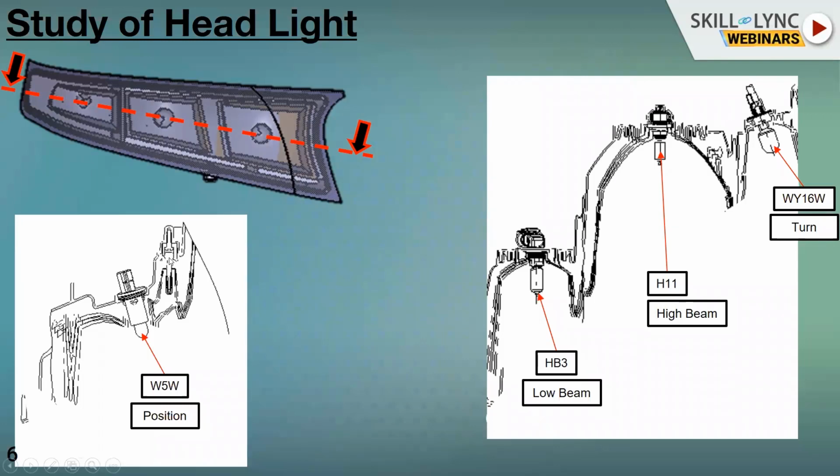For this part we mainly use the PA6 material, that is nylon, because it should be strong enough to withstand the reflector load and hold the reflector. If we go with PC, the stiffness is very low. So we have to choose the right material with higher stiffness, and we can go ahead and choose nylon for this. So this is all about the basic section of the headlamp.